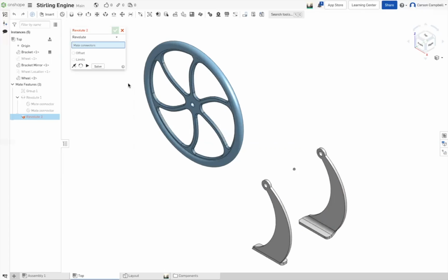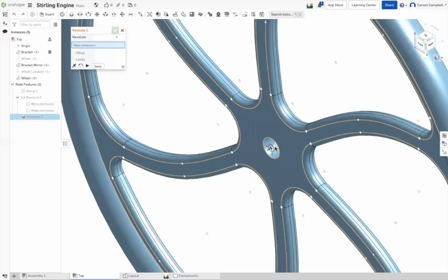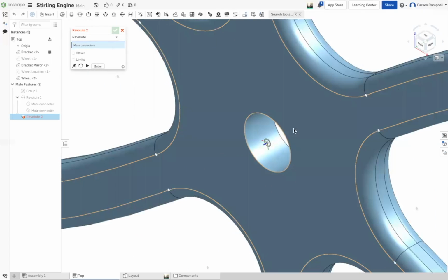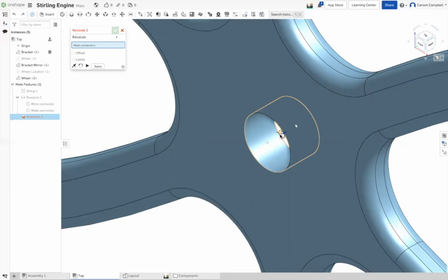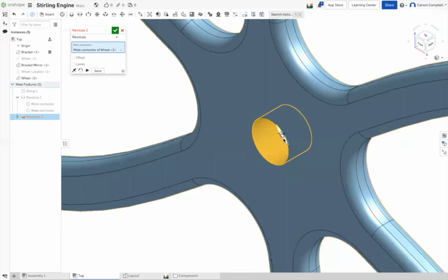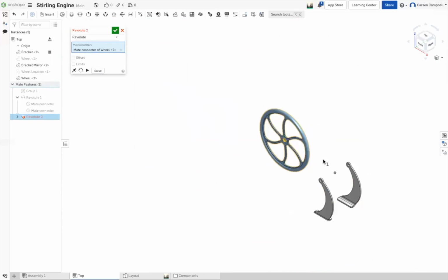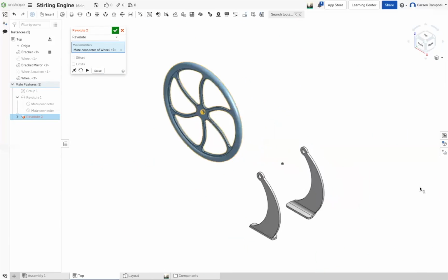You need to zoom in and get the center of that cylinder. Get the cylinder highlighted. Just go around in white space and it'll turn off. Now go directly to the cylinder. There it is. Click that. Okay, so you got that one. It's defined. Now go down and pick. Now scroll off in the direction, and go back to the origin. Go along the direction that you want.